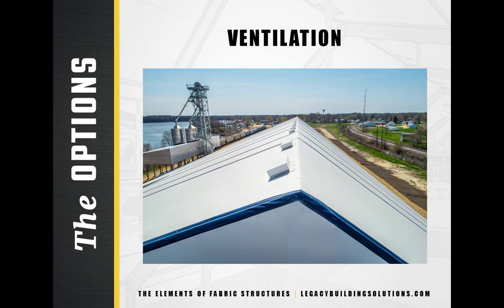Overhangs, which are available on rigid frame fabric buildings, allow for soffit ventilation to aid in the natural ventilation of the building or to provide attic ventilation in an insulated or lined building. They run the length of the building, eliminating dead spots in the center. Varying the widths of the overhangs will control the amount of airflow into the building.